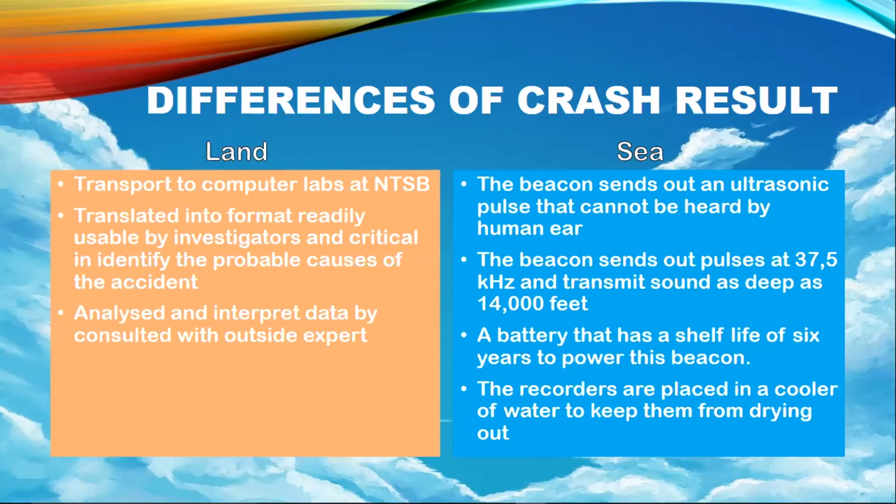But for a crash at sea, the beacon sends out an ultrasonic pulse that cannot be heard by humans. The beacon sends out a pulse at 37.5 kilohertz and transmits the sound up to 40,000 feet. A battery that has a shelf life of 6 years powers this beacon, which begins pinging once per second for 30 days.